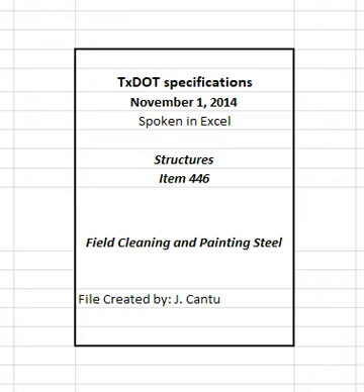4.4 Steel to be painted. Clean and paint all structural steel except weathering steel that is to remain unpainted, unless otherwise shown on the plans. Structural steel includes all main members, bearing apparatus, diaphragms, floor beams, rivets, bolts, lateral bracing, etc., where applicable. Paint the rolling faces of rockers and base plates, all surfaces of bearing plates, and all surfaces of iron or steel castings, whether or not the surfaces are milled, unless otherwise shown on the plans or exempted in this item.